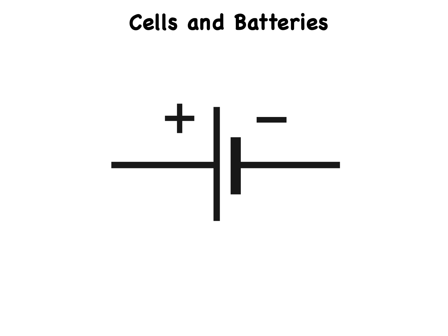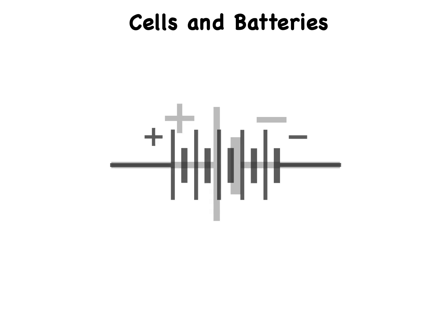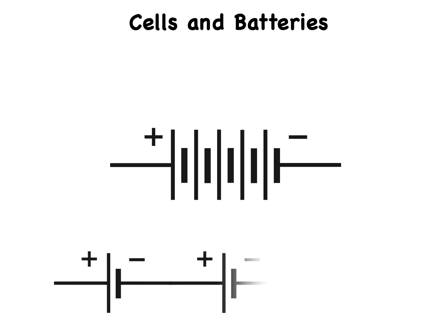Electrochemical batteries with higher voltage outputs comprise multiple cells connected in series, negative to positive in a chain or string, such as this. The multi-cell battery symbol is simply a number of single-cell symbols placed end-to-end without any intervening lines. If a circuit calls for the use of 3 individual, discrete single-cell batteries in a series connection, you might draw 3 cell symbols in series with wire conductor symbols between them. Alternatively, if multiple individual cells are set in a battery holder designed for direct series connection, you can use a battery symbol to portray the whole bunch.